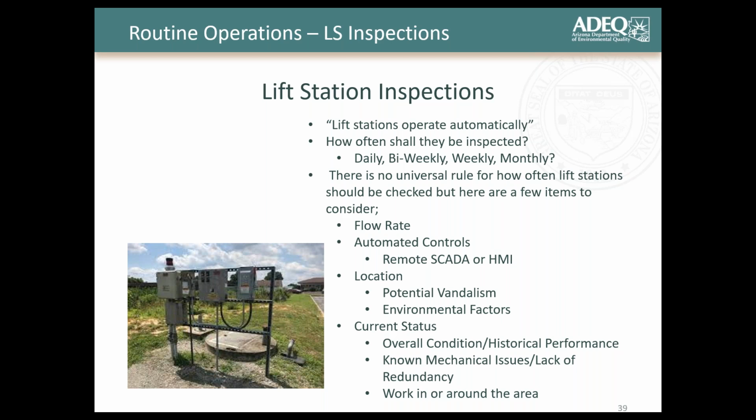It's also going to matter a lot whether you have automated controls. How much can you see on SCADA? Do you have an HMI controller remotely that you can adjust things with? If you don't have those automated controls, you may want to be there a little bit more often. Of course, your location is going to be a major factor on how often you inspect your lift station, right? There's always a potential for vandalism, other environmental hazards, traffic. And then, of course, the lift station's current status.